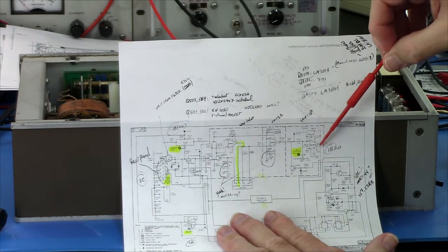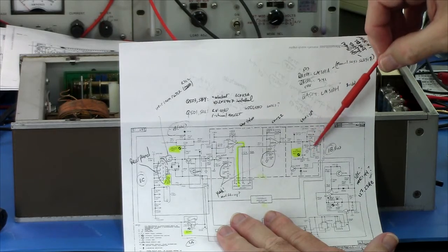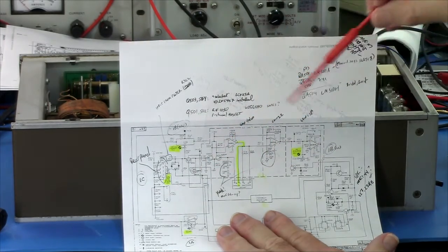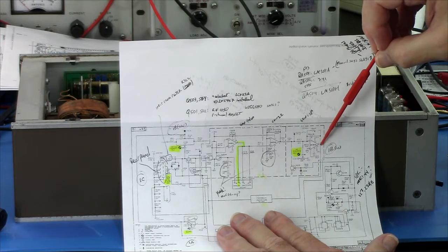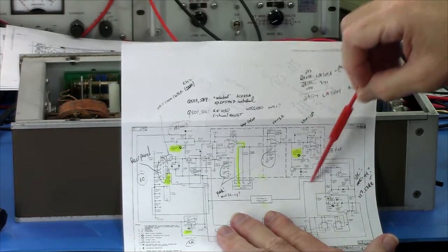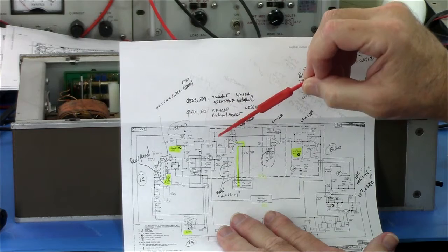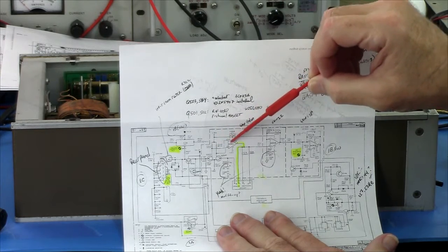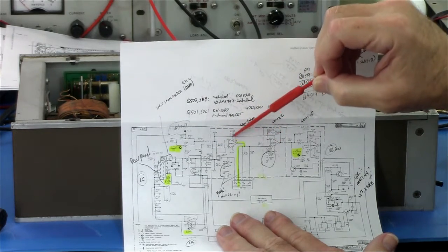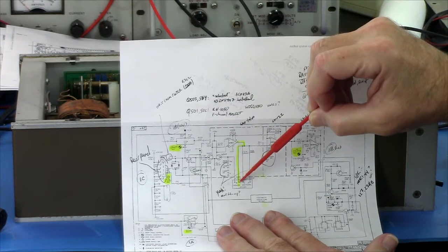What I've done right now is I've taken this op amp out to break that feedback loop, okay? And then I've taken the output, which is pin 6, and I've grounded that. So coming back is 0, and then we can check the output of this op amp on the motherboard.